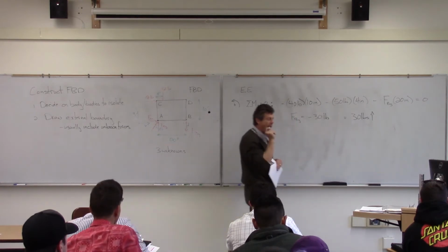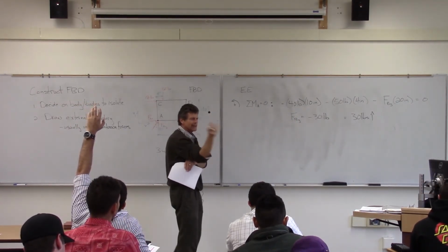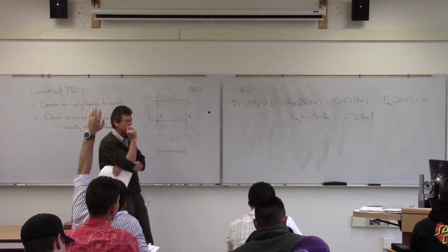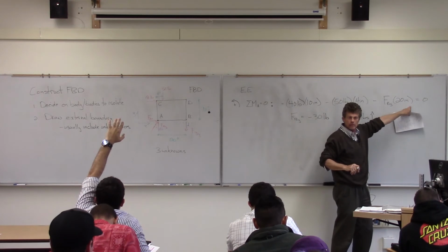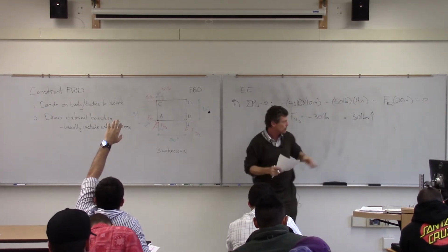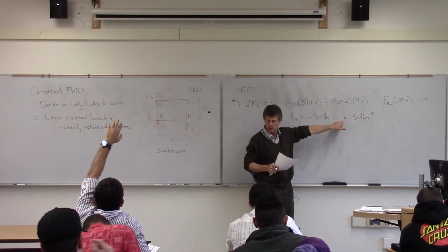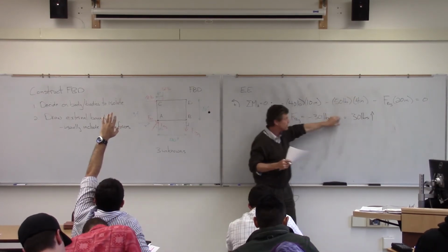Inch pounds. That's a good thing. Think about that. I'm going to move FB over to the other side there, but I got the inches there, right? That's why I say carry around those units, because a force should be in pounds, not inch pounds, right? A moment should be. Everything in here is inch pounds, but good thinking.